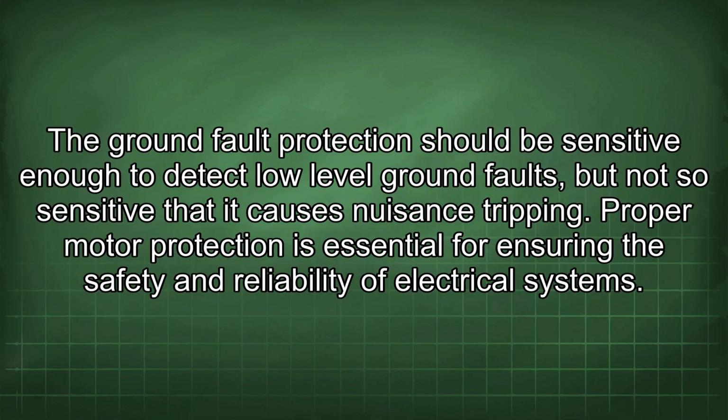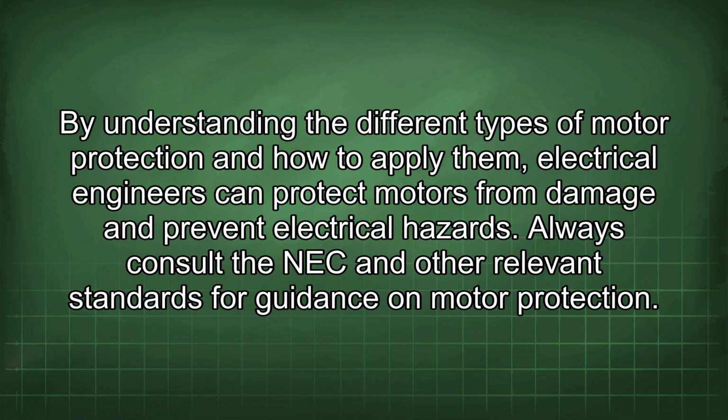The ground fault protection should be sensitive enough to detect low-level ground faults, but not so sensitive that it causes nuisance tripping. Proper motor protection is essential for ensuring the safety and reliability of electrical systems. By understanding the different types of motor protection and how to apply them, electrical engineers can protect motors from damage and prevent electrical hazards. Always consult the NEC and other relevant standards for guidance on motor protection.